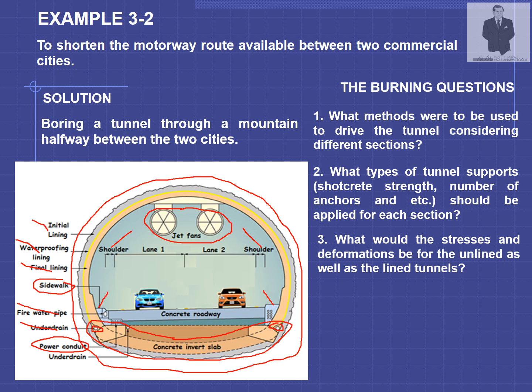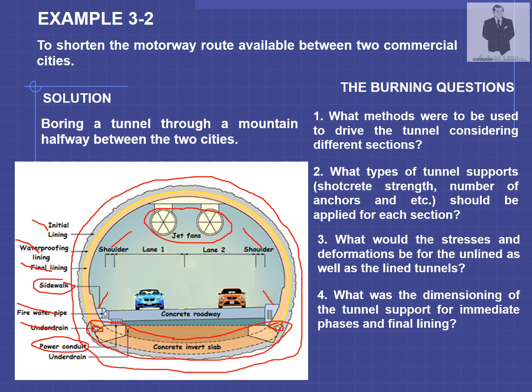And these will cause deformations as well. So we want to know what the magnitudes of stresses and deformation will be unlined, which means without support, and with support. And the fourth question, what was the dimensioning of the tunnel support for immediate phases and final cases?